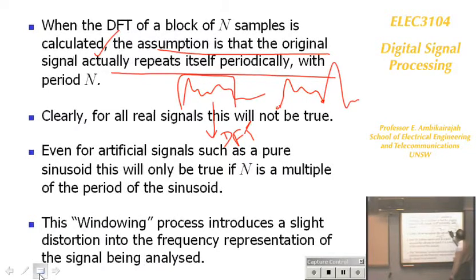That's what the DFT assumes. So you can see naturally the original signal was continuous, nicely continuous. At that point, this has to start again. So there's a discontinuity you are introducing. That is a problem in the DFT. When you take 100 samples or 1,000 samples, you're truncating the waveform, and the DFT assumes that waveform is repeating. That's the assumption of the DFT.